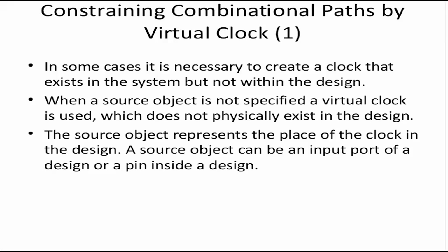There is one other technique, which is called the technique of virtual clock. I'll just discuss this technique for now. You could choose to study more about it and use it in your synthesis, or you could choose to use the set max delay. It doesn't make much of a difference for synthesis. However, virtual clocks are very much useful for timing analysis. When we go to unit 5, we'll know why. So I'll just list down the method.